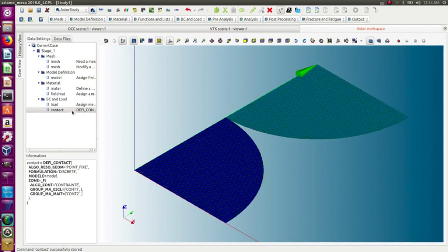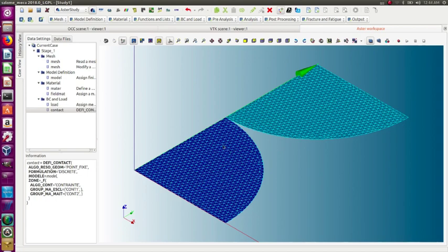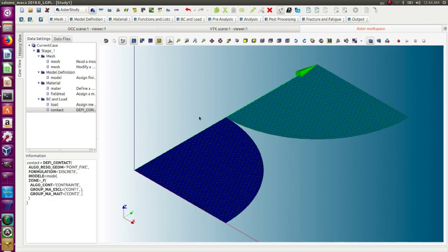Okay, so let's see what we have now. This analysis will be a nonlinear static analysis, so I also need to introduce two things. I need a function that gives me the number of increments I will divide my load into to make the nonlinear calculation, and I need another function, a ramp, which will be multiplied by the load and tells the solver that at each increment my load will be multiplied by this ramp function and calculated slowly. So it will not apply the load directly at the first step. That's generally the way to make this kind of nonlinear static algorithm converge.